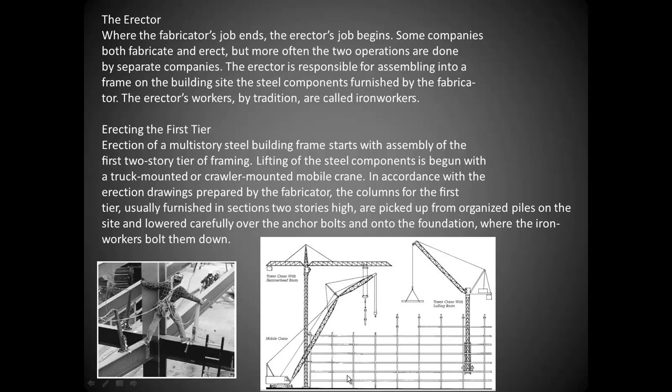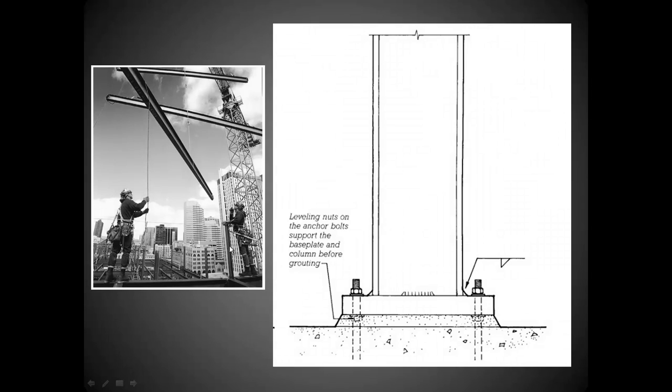And so anyway, we can see he's got some wrenches. What we'll see further on here is these are called drift pins. The drift pins, they'll probably have one or two on their belt with a wrench end on one end to kind of get things started. As the steel gets set in place, they use these drift pins, which are basically tapered needles, to line up the holes on the steel as it gets in place. They're long enough so that they can work the steel back and forth to make it work.